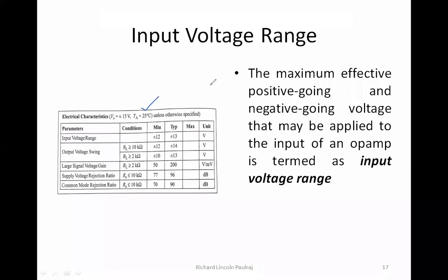Yes. So every degree rise in temperature will actually impact the voltages. If I'm taking 25 degrees centigrade as the standard, and I operate at 26 degrees centigrade, then the output voltage that I'm going to expect is going to be completely different from that at 25 degrees centigrade. So approximately, there is going to be about 10 millivolts of difference.